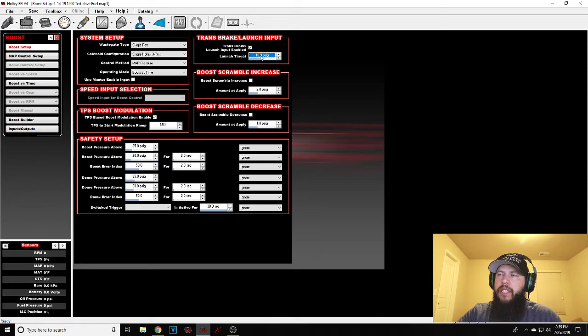The 10 PSI target when you're on launch control. You have to be careful with what that does to when you let go of the button. It doesn't reset the feedback on the duty cycle. So if you don't have a bunch of timing pulled, if your car needs it, I mean, you may have a big old motor and it makes 10 psi pretty much no problem, and it's just using the solenoid to regulate yourself at 10 psi.